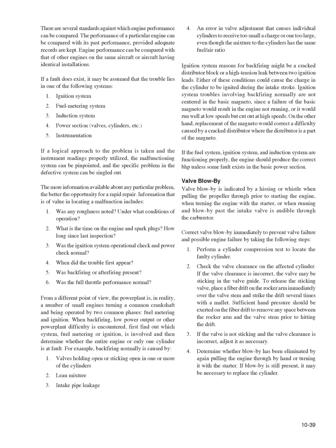For example, backfiring normally is caused by 1. Valves holding open or sticking open in one or more of the cylinders; 2. Lean mixture; 3. Intake pipe leakage; 4. An error in valve adjustment that causes individual cylinders to receive too small a charge or one too large, even though the mixture to the cylinders has the same fuel/air ratio. Ignition system reasons for backfiring might be a cracked distributor block or a high-tension leak between two ignition leads. Either of these conditions could cause the charge in the cylinder to be ignited during the intake stroke.